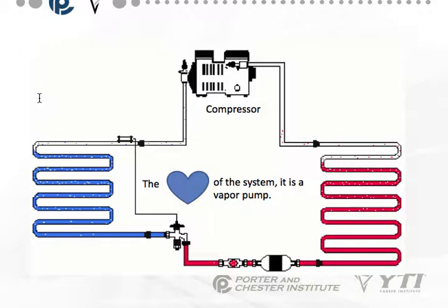The other thing to remember is that it cannot pump liquid without damaging the internal components. Liquid refrigerants do not compress, okay? So it acts like hydraulics. If you try to compress fluid, it's going to exert outward pressure on parts and components, and they're not built for that.